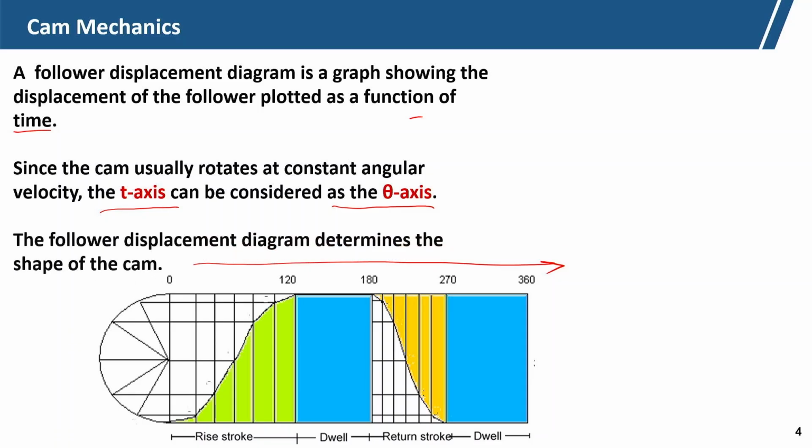The follower displacement diagram determines the shape of the cam. So, this is the follower displacement diagram, and it will actually determine the shape of the curve. So, we can have the follower displacement with a certain requirement, and from there we can get the cam profile.